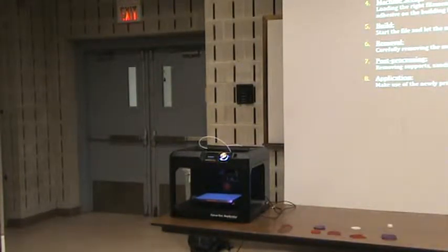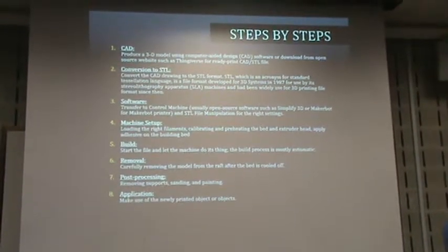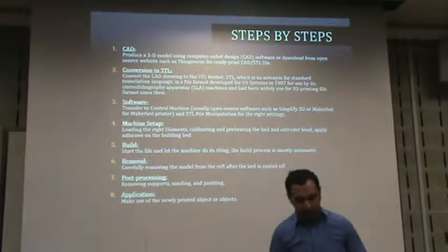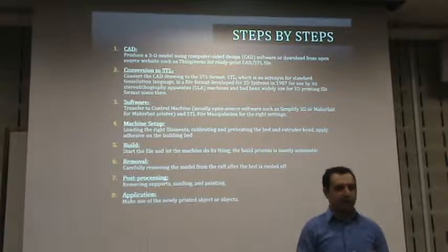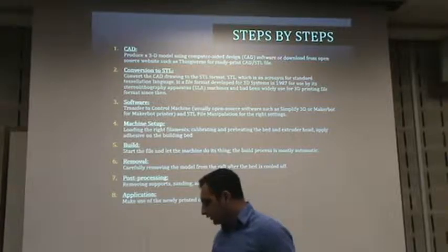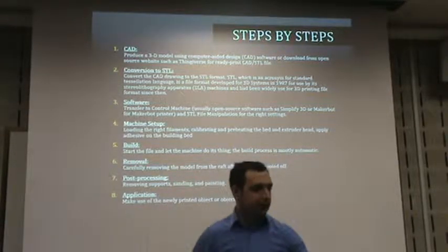So I think in this case you don't need most of the post-processing. The only post-processing probably would be to take off, in this case, the bottom 2 layers, the raft as I spoke of. That's pretty much it. And there is nothing else. This is an example of a raft.